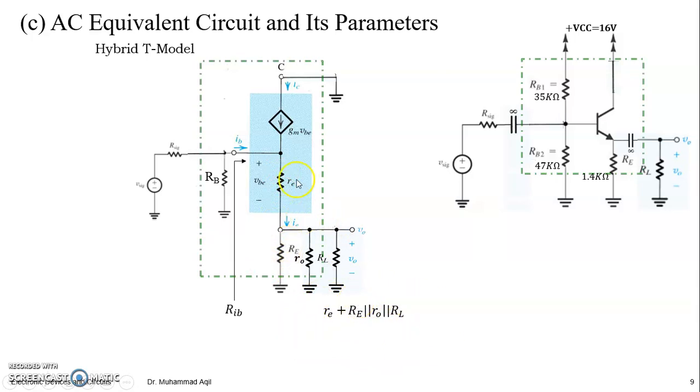But when we want to see this resistance into the base, then it will be reflected or felt as (1 plus beta) times what it is at the emitter, right? So at the base side it will be (1 plus beta) times higher than at the emitter side.